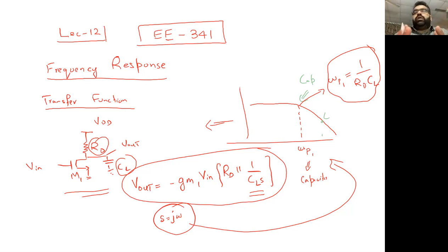So as an engineer, you need to see which capacitance is basically affecting, for example, the first pole, and then you can tweak that thing, because this first pole is ultimately the 3 dB frequency of the system. And if you can reduce it, then what's going to happen? Your frequency or your bandwidth is going to be reduced. Similarly, if you bring that to the wider side, if you have something like this pattern, your bandwidth of your system is increased.